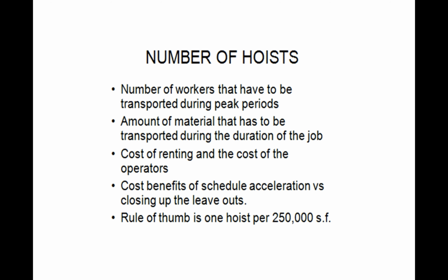Because also for these hoists, as you'll see in a bit, you have to leave outs in the facade of your building to accommodate these hoists, and that's something you have to go back and basically do at the end of the project, and it has an effect on your productivity because you're bringing back crews to do small bits after they have already done the majority of their work earlier. So you could get a new crew in, a new bunch of folks who are just learning the nuances of your job and the materials. So there are drawbacks to having too many hoists as well.